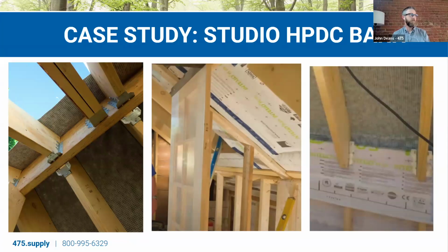So this is just taking a little bit closer look at the Mento Plus. You can see on the underside that reinforced fiber in there. So that makes it a very strong weather barrier, but it also allows you to dense pack insulation against it. It's not going to sort of stretch greatly or risk tearing. You've got that reinforcement there. And then you can see when I got these pictures, they didn't have it yet. I think it's up now, but they're putting Mento Plus across the underside of those rafters, and then going to be filling the cavity with insulation.